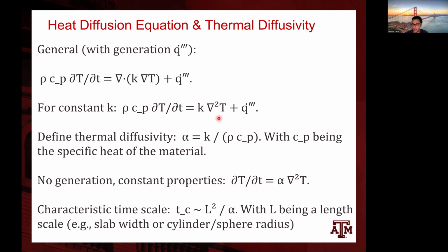So we can write the law in this form regardless of whether we are going to talk about it or solve it in Cartesian, spherical, or cylindrical geometry. And then this is the volumetric heat generation rate, meaning heat generated per unit volume, per unit time, or per meter cubed per second.